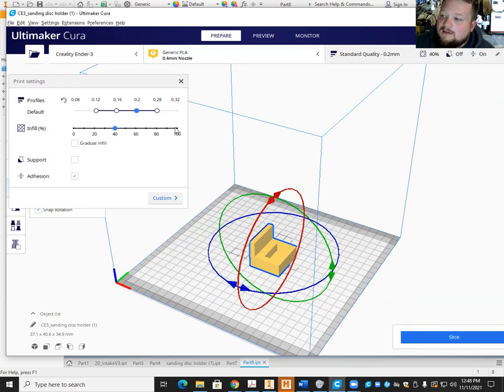And the percent of infill. As you increase the infill, you're going to be spending a lot more in plastics. You're going to be spending a lot more in the time it takes to print. So something right between the 10 to 20% really generally works pretty good. This is a 20% infill. This is a 10%. This one's a pretty small part. It's not a big difference to go a little chunkier. So I'm going to go with a 20% infill.